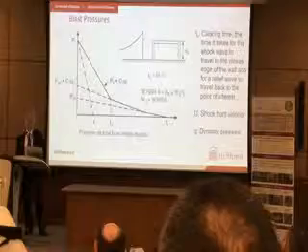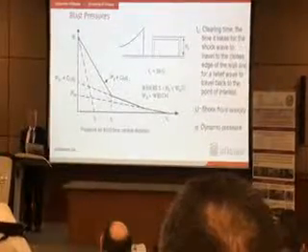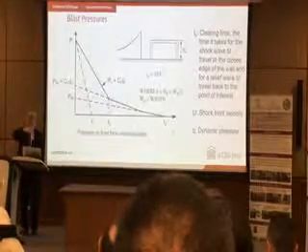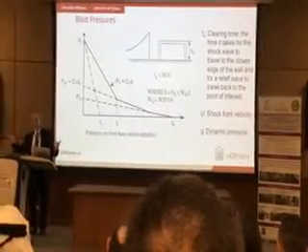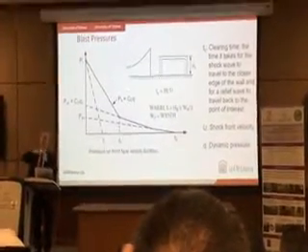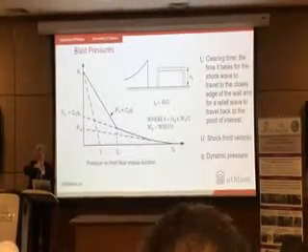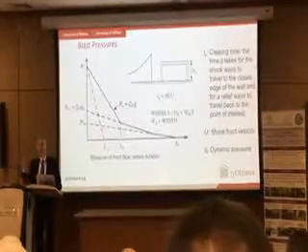Impulse is very important. In fact, if you go to extreme impulse, which means if you make this horizontal axis very long, then it becomes impact. Impact factor in engineering, we usually use about 2, right? If you apply same load statically, you may get P. If you do it very quickly, if a car impacts a building, then you multiply it by 2.